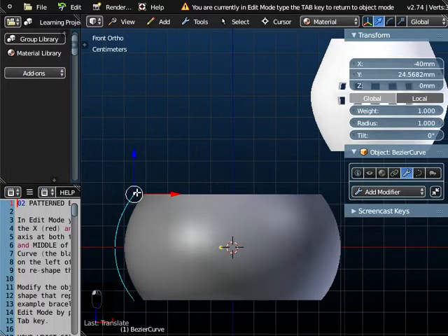But what you can also do with these control points is, if you look in the transform panel over here, this Y value is 24.5682 millimeters at the moment. If you want this accurate, you can type in 25 mm for millimeters, and that will give you exactly 25 millimeters vertically. And similarly, if we select the one at the bottom, you can see it's minus 24.